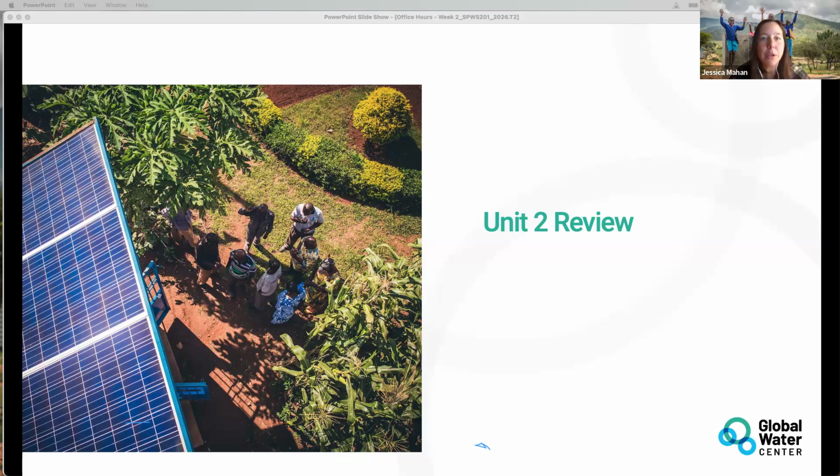And as Zerhoon mentioned, it's a step test. So essentially you start off at a lower flow rate. So like he mentioned, maybe 4 meters cube per hour. And then every few hours you increase your pumping rate, increase your pumping rate, increase your pumping rate, right? Until you find what that maximum might be. Basically is where your water level is stagnant, right? Where your water level stops going up or down as much when you hit that rate.